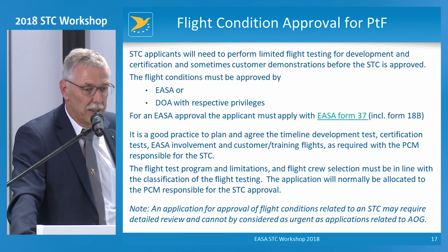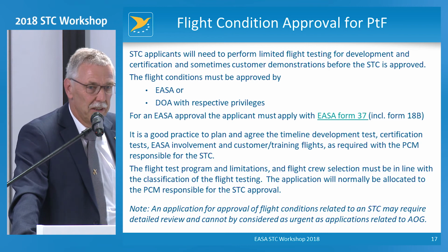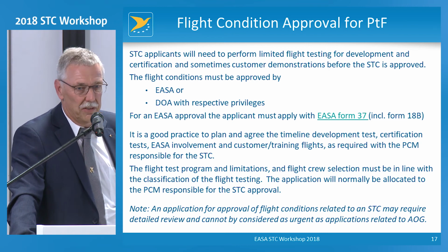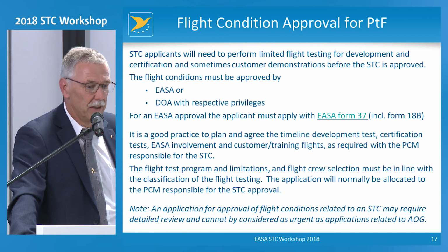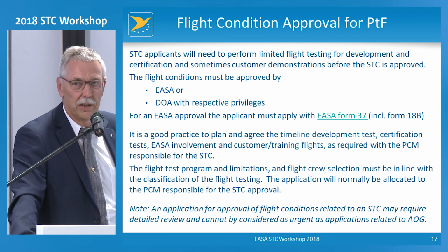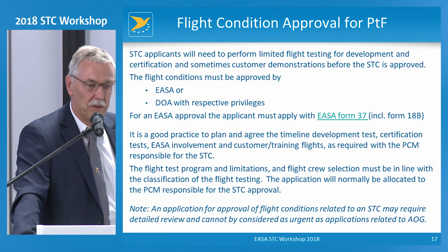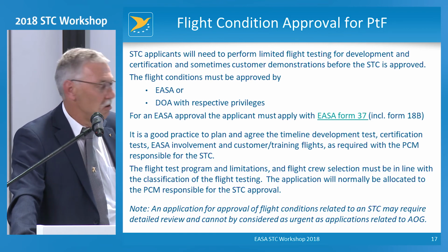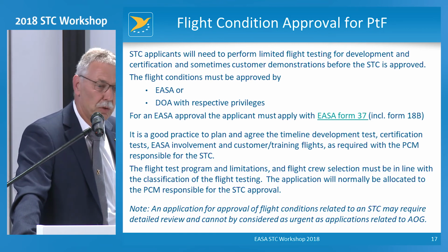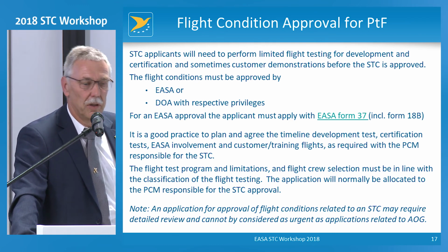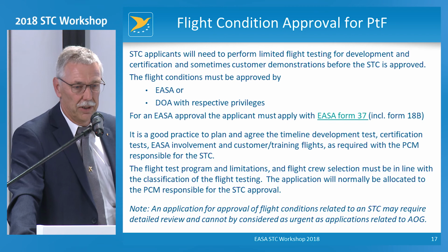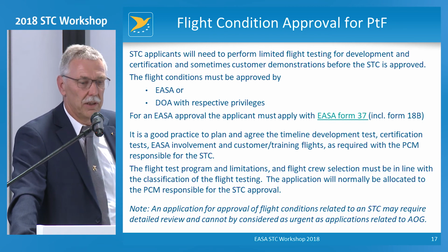However, I want to say that for STCs, we would typically not see this as an AOG, because you can plan early, and it's good practice to plan early and to discuss with the EASA team the flight test requirements, the flight test program, who can fly it, what kind of test pilots, and so on. And also the level of involvement. This would mean it's early enough and you can plan for it, and it's not an AOG case.